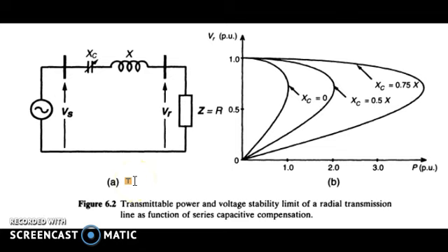The fundamental difference that we have discussed between shunt and series compensation is, one, how they are connected in the transmission system. Another is the effect by which they compensate. When you add a shunt compensation device, it acts as a current source which injects a controlled reactive current that provides whatever reactive power is required by the system so as to improve its performance.